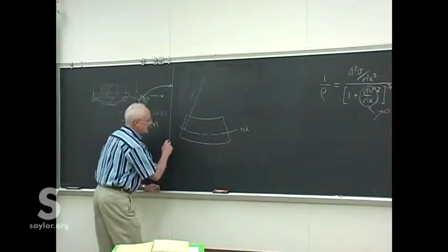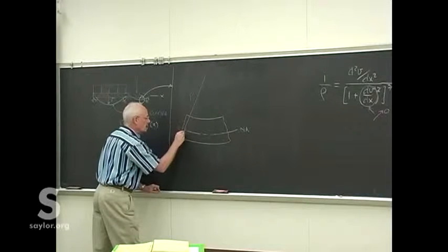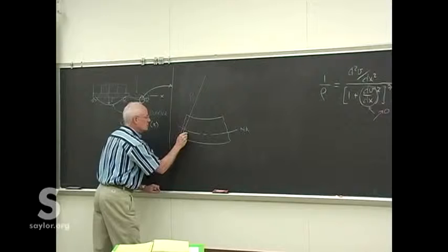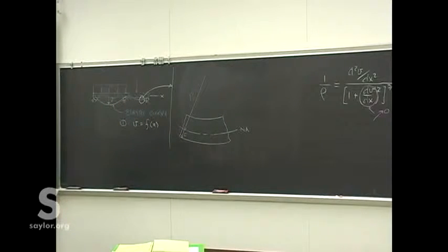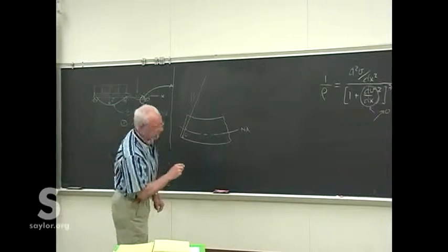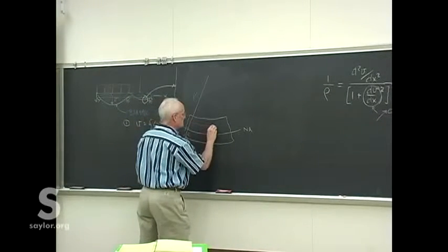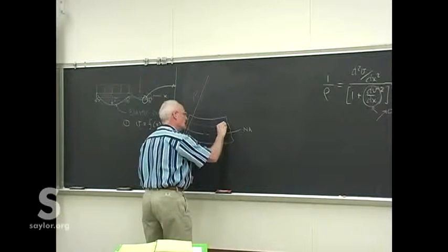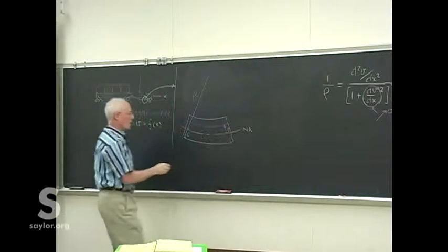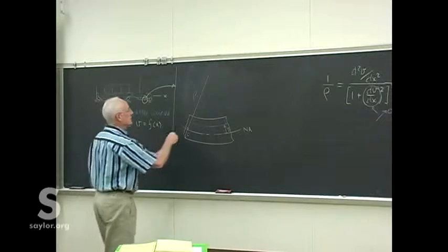And then, depending on which way we're going, don't forget that from the neutral axis to the extreme part of the beam, we always call that C. But anything else in between, we called Y. So let's just go up to some arbitrary point, Y. And in fact, for our measurements, that's actually in the negative direction.